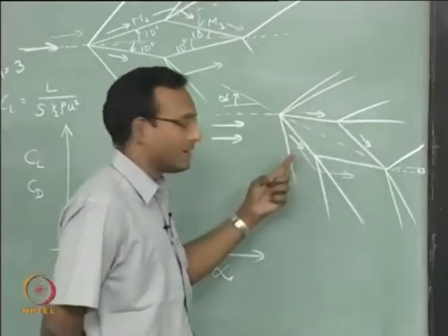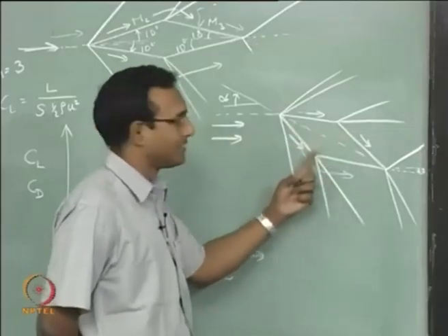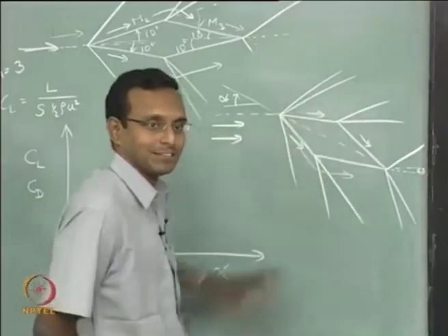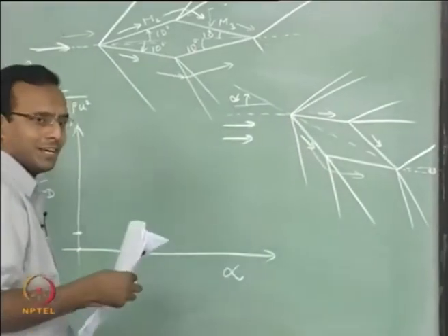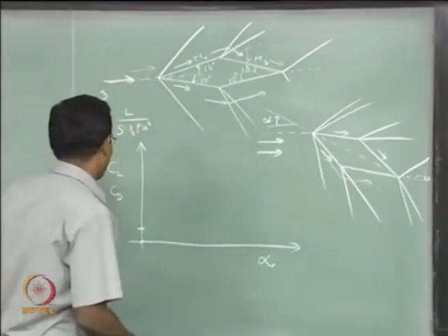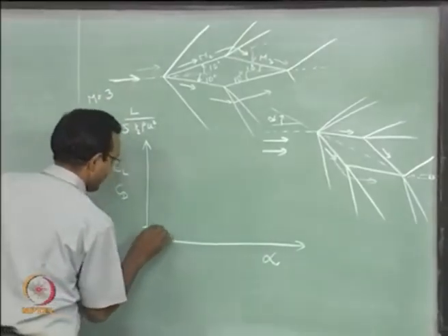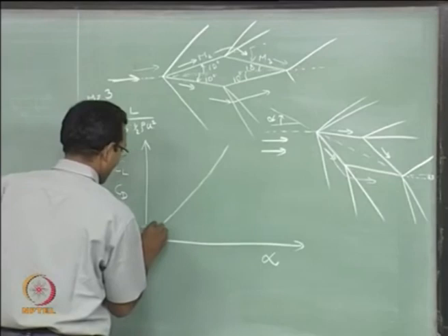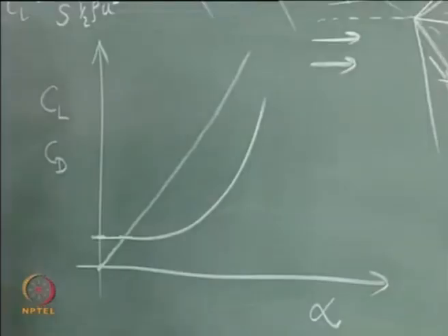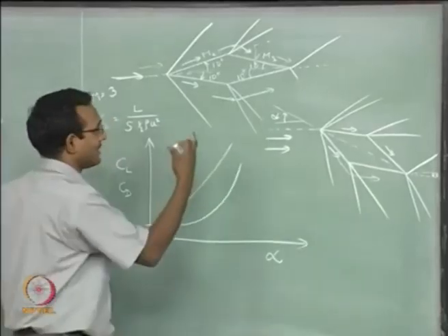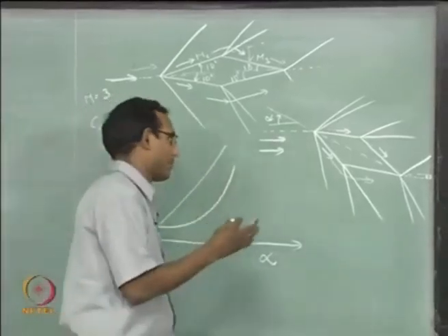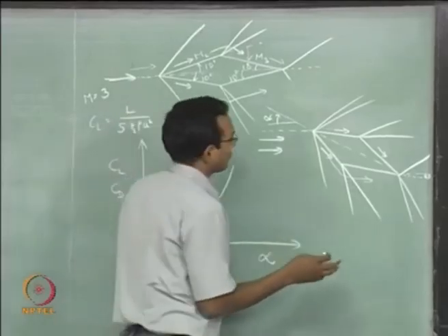Overall there will be a moment, and this net force will be the sum of these two forces, that will be like this component is the lift, this component is the drag, all that is sitting inside that. Okay. You can solve this problem. I would say I am going to give you exercise on the web where you can solve this whole problem. If you look at what it does, lift is going to increase slowly while drag is going to start slow but increase drastically. This is what will happen. Okay. I will show you actual data for this 10-degree angle with Mach, I think it is Mach 2. I have a plot of that, we will show you after some time.